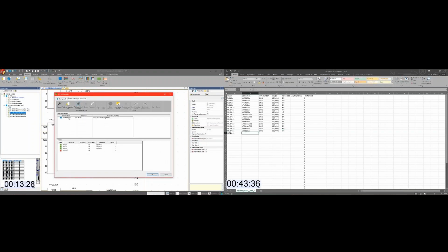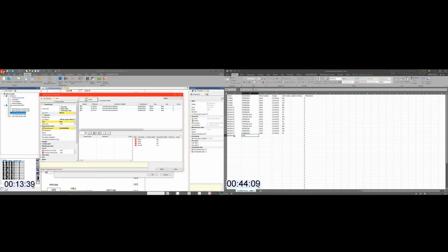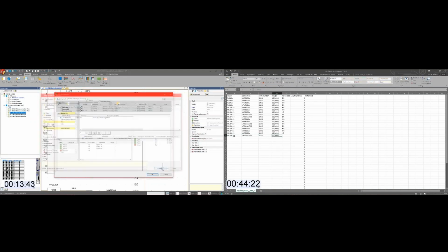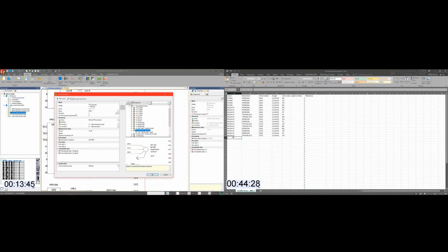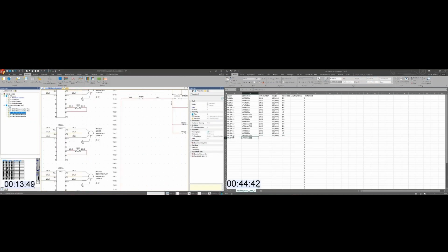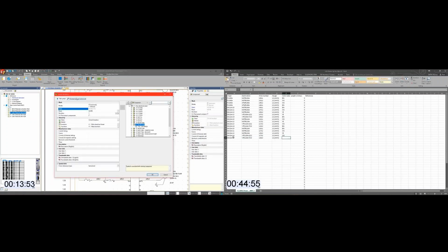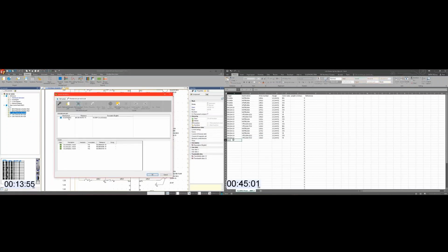So I have documentation created, etc. All I have to do in SolidWorks Electrical is simply come over and make the change in one place. So I've removed that part number. The symbol isn't related to that part number. So as I assign a new part number, in this case, a 25 horsepower motor, all those properties come over and will populate and update into the existing symbol. So that part number has been updated to reflect that. I'm also going to change the part number inside of this circuit breaker.